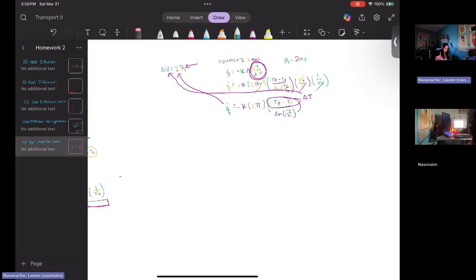If we divide over and multiply over all of the expression that we don't want near our change in temperature, we get that our change in temperature is equal to our heat flow multiplied by natural log of our final radius over our initial radius, divided by negative thermal conductivity multiplied by 2 pi.